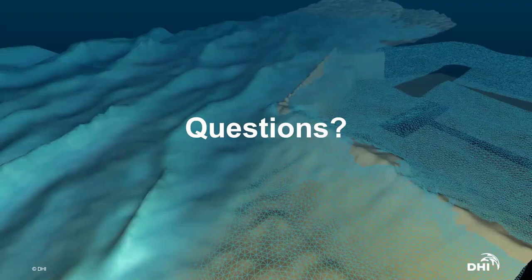Thanks a lot, Joachim. In the slide which explained the overtopping from porous breakwater, does the geometry of breakwater change at different time steps because of changing the layer thickness? So yes, that is something that it does. Since we have this sigma layering system, when you try and map the porous breakwater, what the model does is it tries and tests which cells are within the mapped area, and those cells are then used in the calculation.